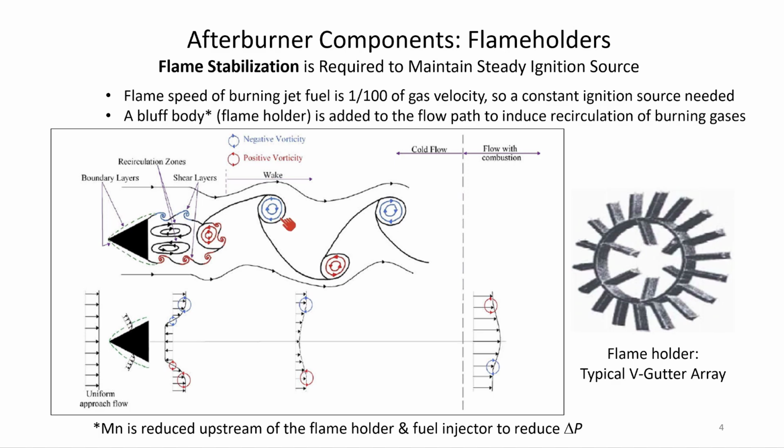And what happens is there's eddies that shed from this bluff body. It's alternating hot and cold, and what ends up happening is that this is a piloting source for the rest of the flow field. And if you look down at the bottom picture, you can see that for one instant there's flow going forward, and then there's flow going negative, and it alternates.